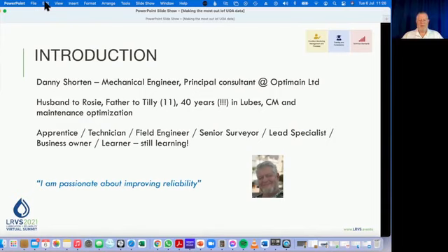We don't look after the oils, we don't understand how the oils are telling us about the plant. So there's a deterioration in reliability opportunity due to poor management of lubricants. And I believe wholeheartedly that we can get more bang from our buck by managing our lubricants better. Now, what we don't do is look at our assets very often as a population, and we'll get back to that because I think that gives us a little bit of a spin that we can take advantage of.